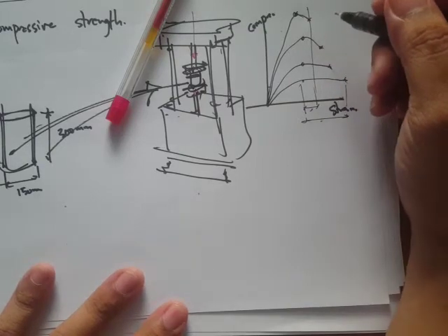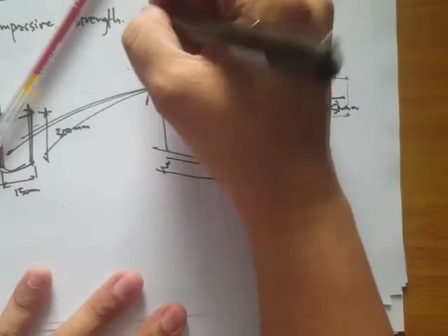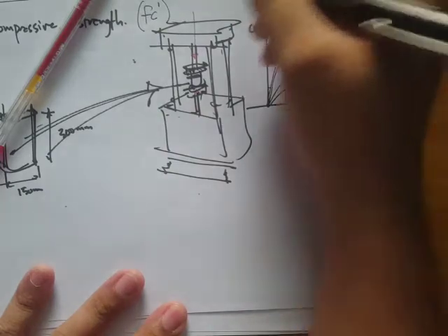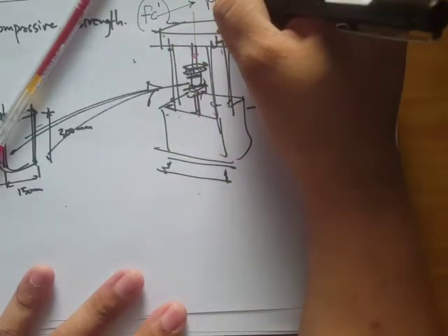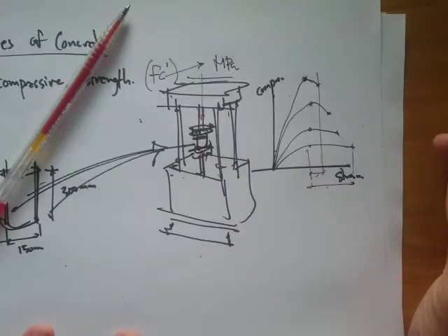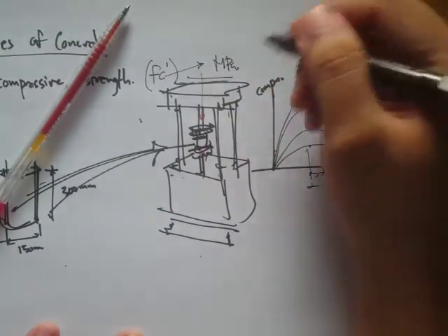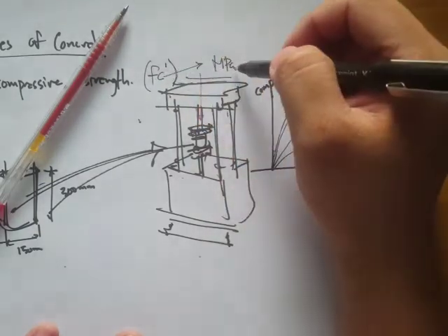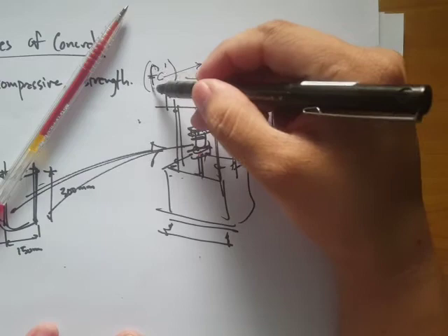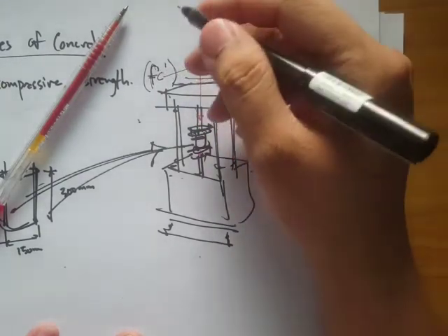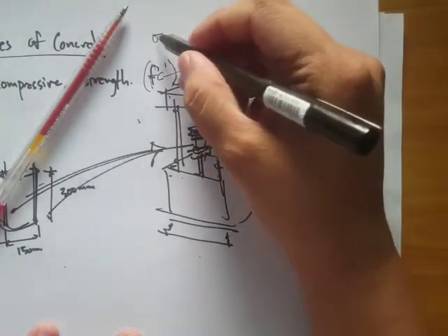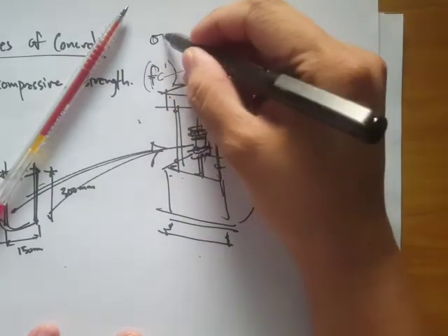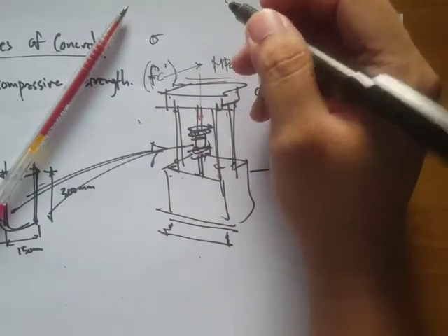Of course, you get high compressive strength, but the ductility, or the brittleness, is affected. The compressive strength of concrete is written with the symbol f'c, and the unit is megapascals. You just have to get used to this notation for stresses, written as f'c, unlike in our strength of materials course, where we use the stress symbol sigma.